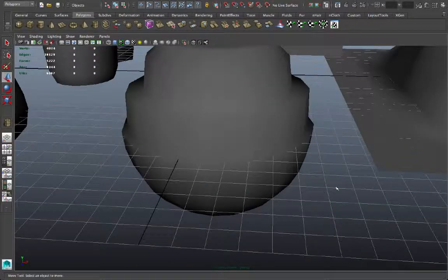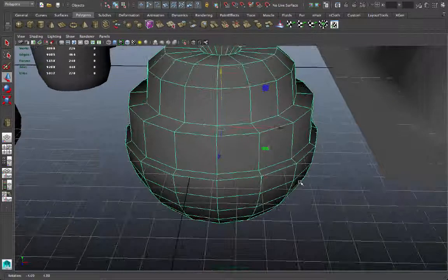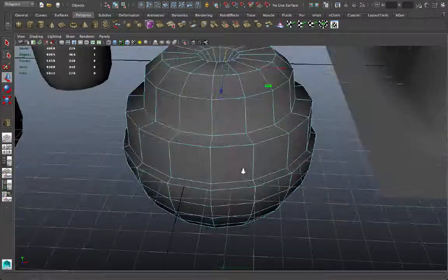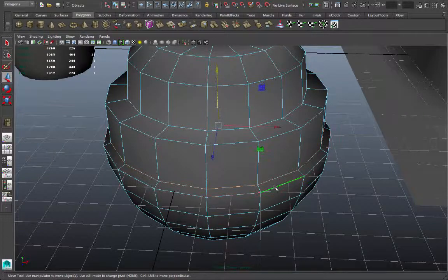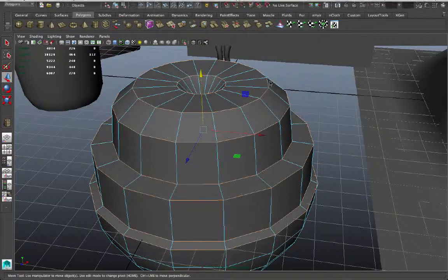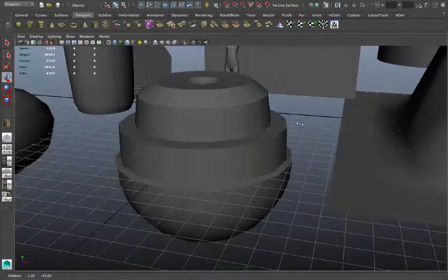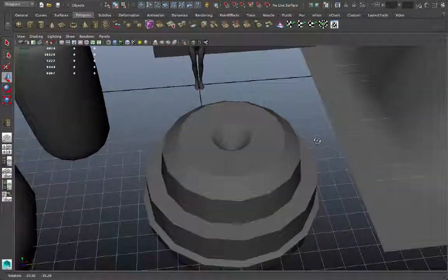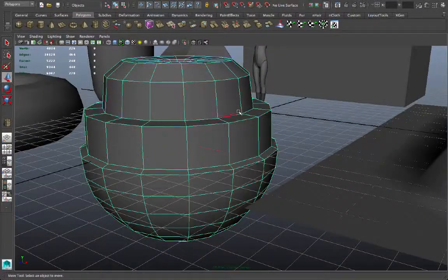Now again, by default that sphere was very soft-edged. But let's say I want to make all these ridges into sharp, hard edges. So I'm going to select all these rings by Shift double-clicking them. Just the rings, Normals, Harden Edge, and then you can see we get a very stepped look, a very kind of mechanical look. But that's okay, sometimes you want a sharp edge.